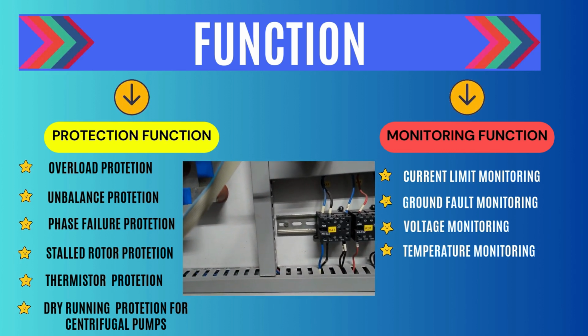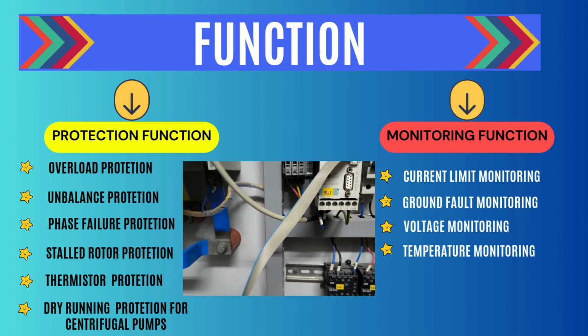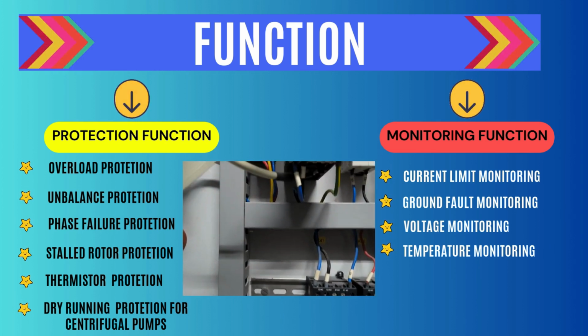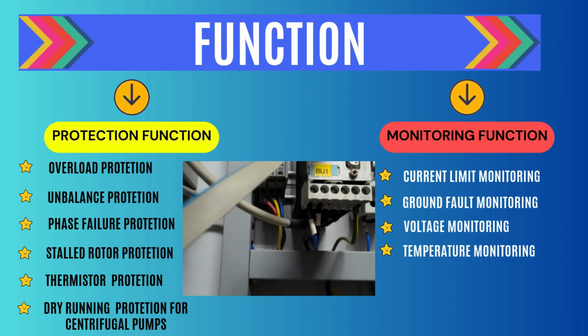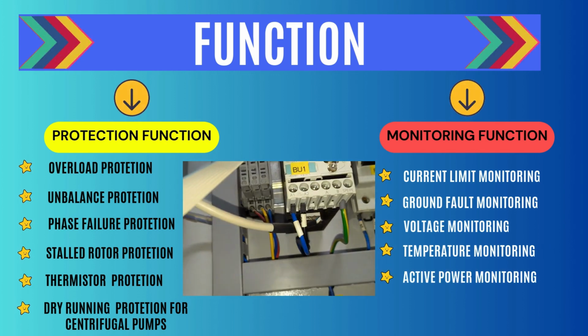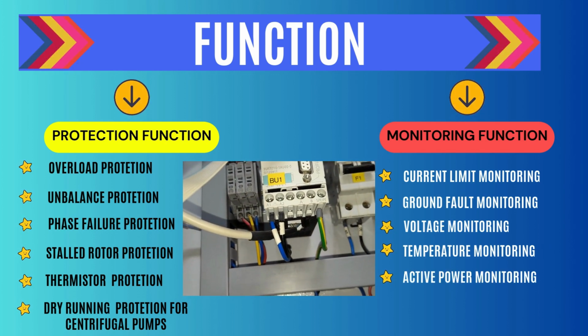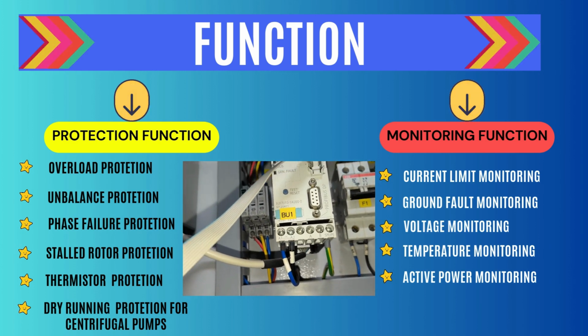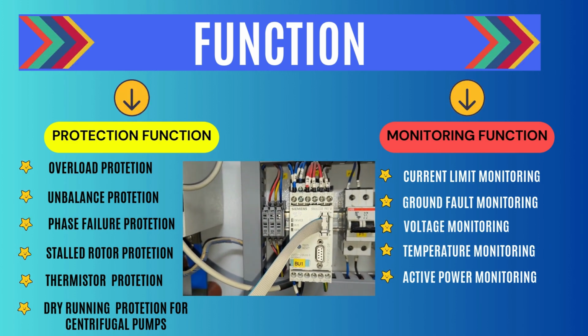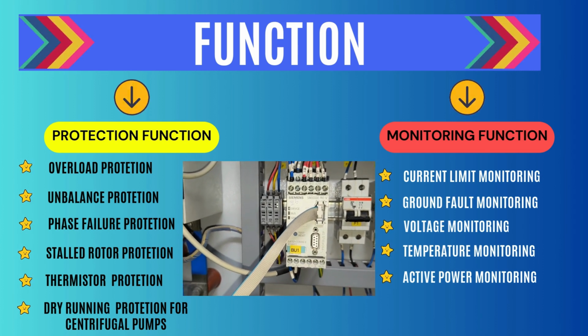The active power curve of a motor reflects its actual load. Excessive load results in increased wear of the motor, and thus may lead to premature motor failure. Power factor monitoring. The power factor fluctuates more than the motor current, particularly in the low end performance range of the motor. Monitoring operating hours, stop time and number of starts.